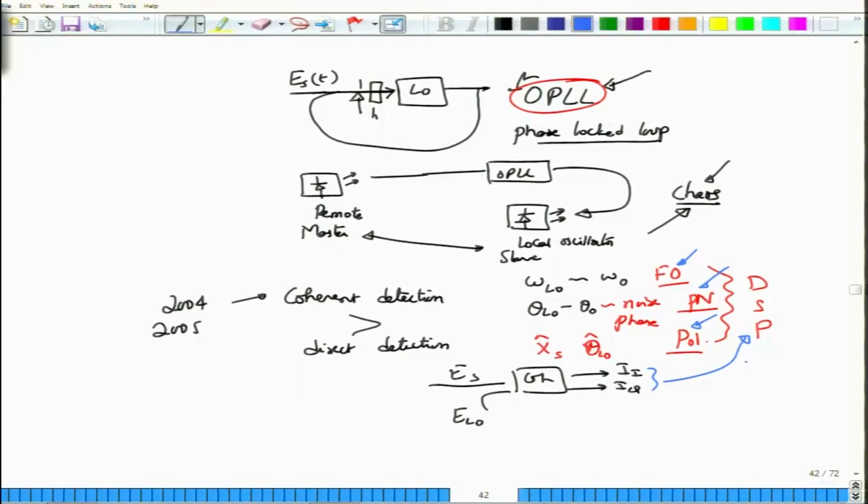Granted that most of these DSPs are not real time, they are what is called quasi real time, but in principle, using these DSP algorithms you do not have to implement optical phase lock loops, and this is actually a big achievement in fiber optic communications over the last 10 or 15 years. This is a very important development, and it has made it possible for us to reach data rates of about 100 gigabits per second and beyond. Okay. We will look at some algorithms for frequency offset, phase noise and polarization tracking in the later modules.